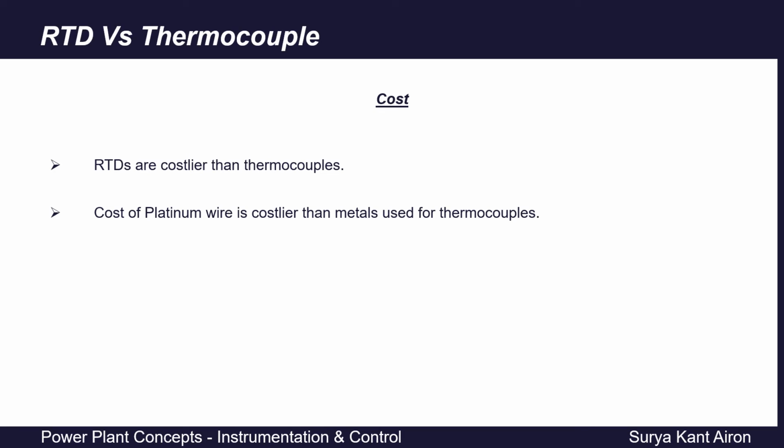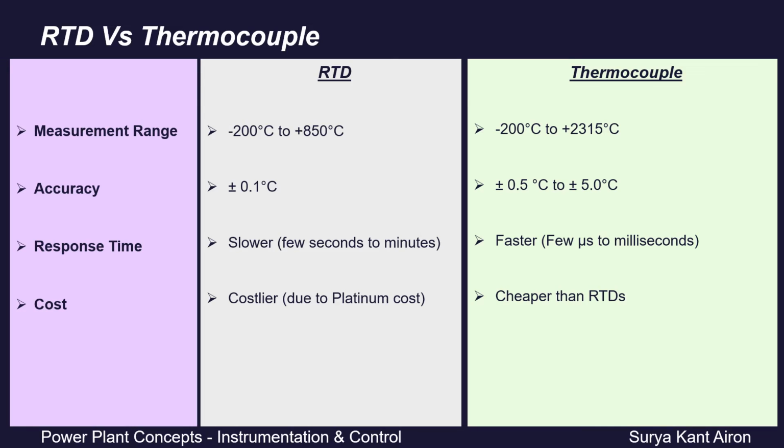One more thing, if a temperature measurement is used for overall plant protection, for example our HP main steam temperature or reheat steam temperature, where a very high temperature can increase the stress level on the main steam piping, we may have to either initiate a gas turbine load reduction, or in the worst case we may have to initiate our GT and HRSG shutdown.